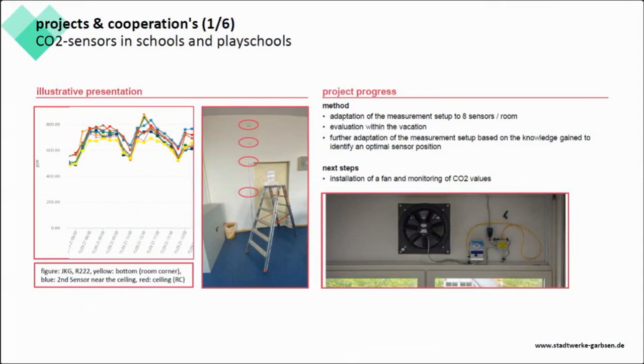The picture in the middle shows the arrangement of the sensors in a line, and the right picture shows an actual development. We will equip one of 2 similar rooms with a ventilation, and we will monitor the sensors to get to know how efficient a ventilation is for CO2 concentration and for decreasing the infection risk, especially in the now beginning autumn time with uncomfortable air temperature outside. Next slide, please.